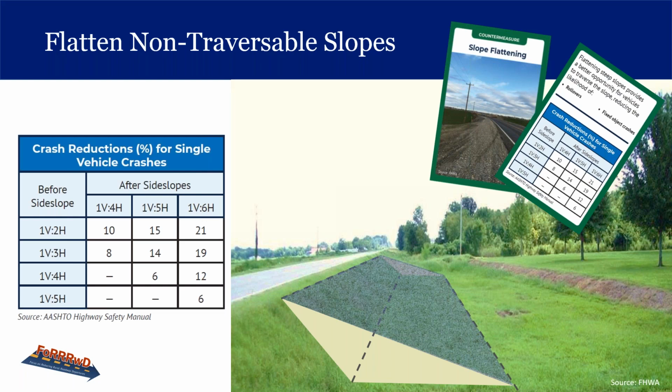And so let me see, did I go one too far? There we go. So you see how they improved it, and then you can kind of see what it was like before. Like this area here, you see how steep it is. So that's how it was when Morgan Freeman had his crash. But since then, they've paved the shoulder and created a more traversable slope there. It was 4.5 to 1 when they filled it and created a slope. So 4.5 to 1.